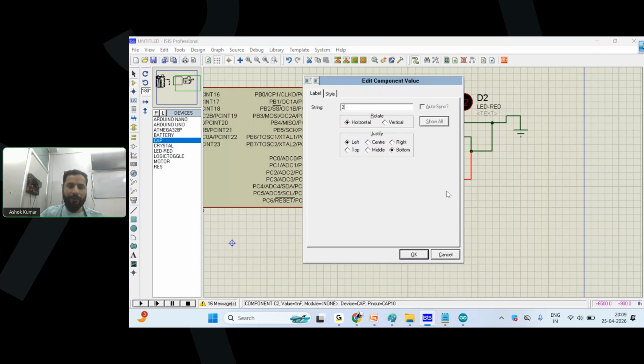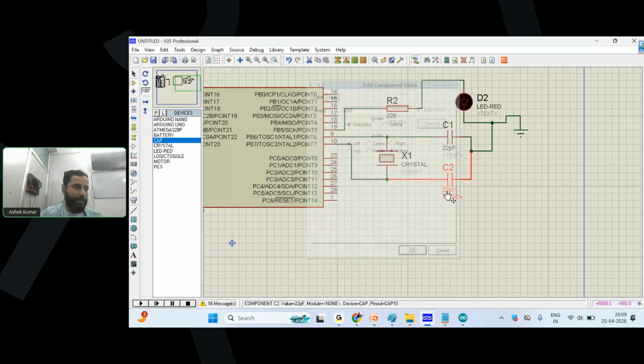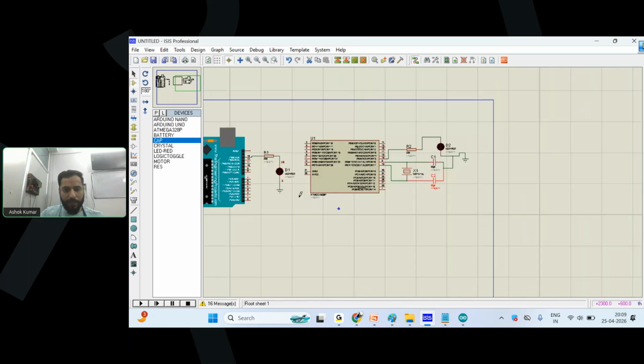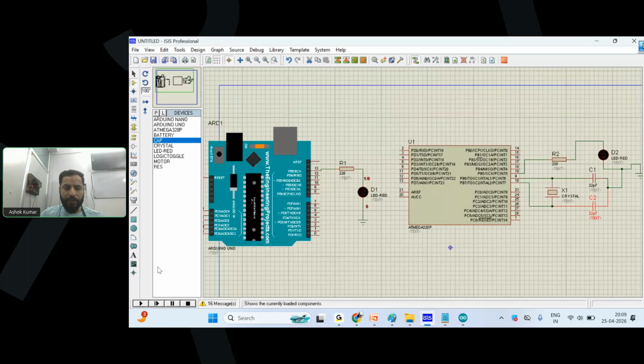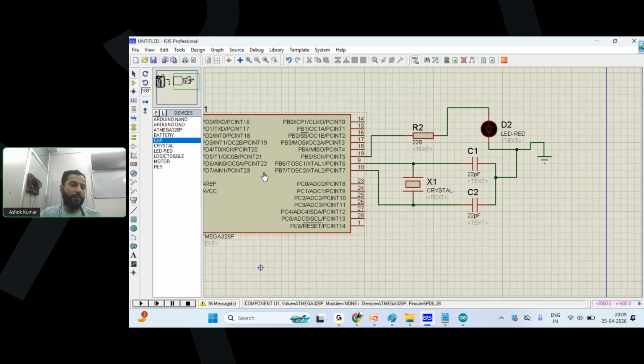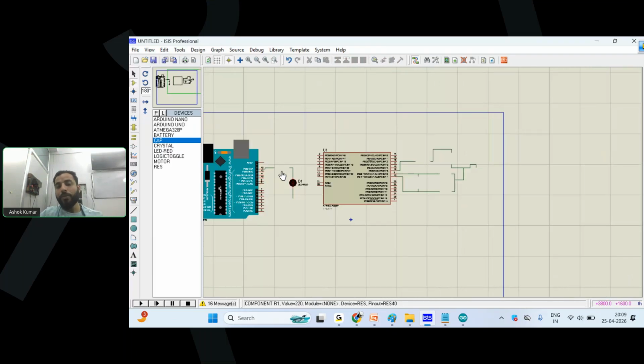So now as we have connected the external crystal oscillator, it must work because we discussed the clock frequency. So we have connected this. Now let's click play. It's still not turned off after a second, because it's not only about the external crystal oscillator. We also need to change the fuse settings of this controller. And how to change these settings? As I mentioned, I'll use this board only for 1 or 2 programs. After this, I'll completely switch to this one.